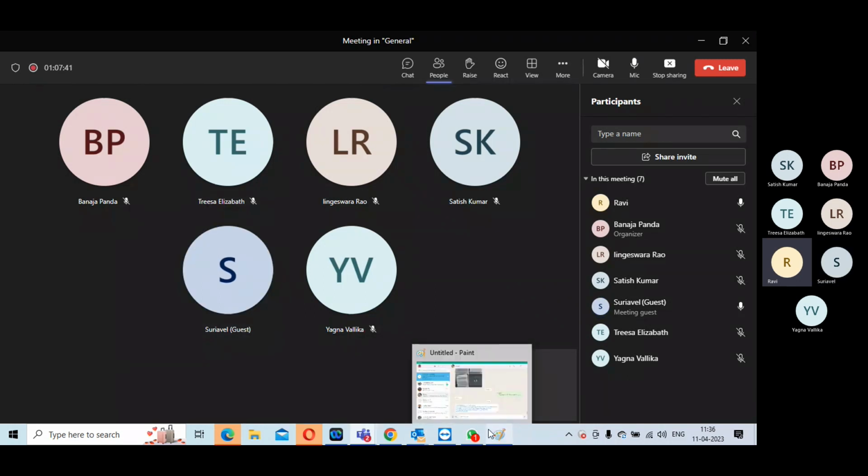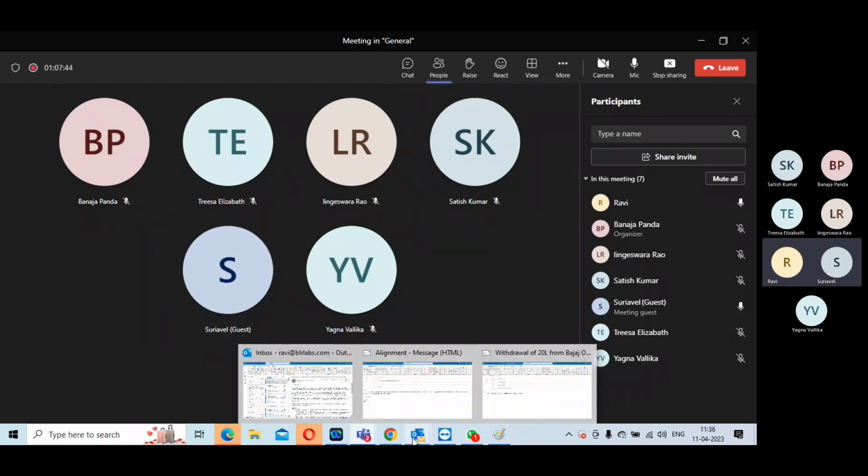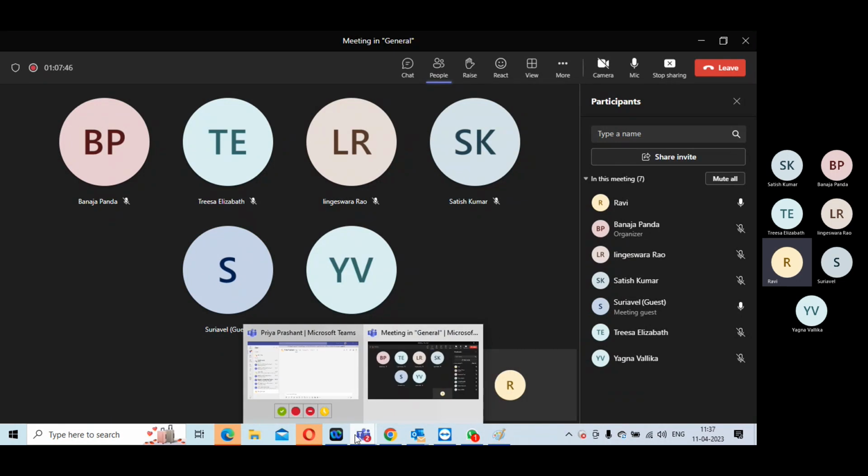Okay. So up to what stage? Good question. Let us say your placement condition is good and your power domains are all fine. At placement, you are thinking that your floor plan is good. The maximum stage that you should look at is up to CTS construction. Beyond that, if you are seeing something in routing or certain things, then you have to come back with blockage adjustment, not to do with any memory position or anything. Your memories or IOs should be frozen by the time you have got your first CTS criteria.